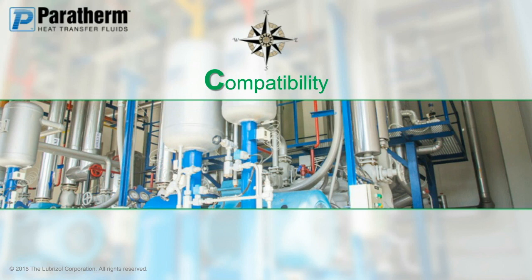So you're going to want to really work with a supplier on that. You need to look at all materials of construction for compatibility, because there's a pretty clear line between what's compatible with aqueous fluids and what's compatible with non-aqueous fluids.